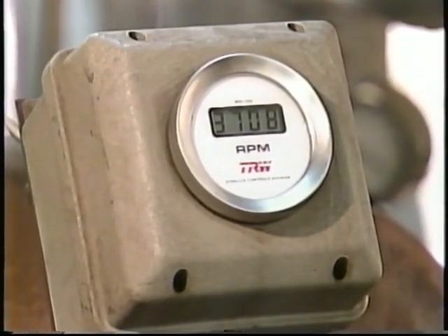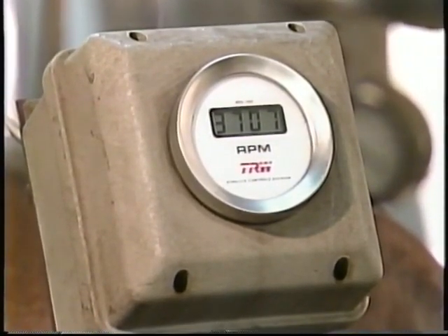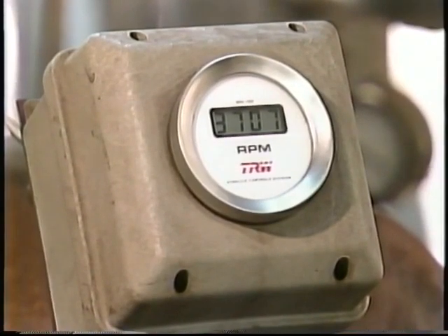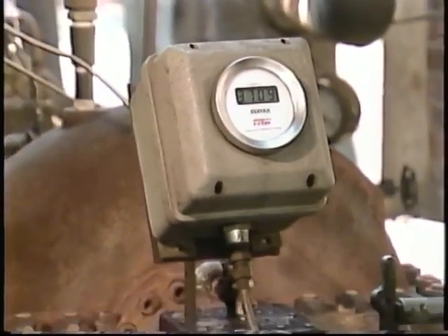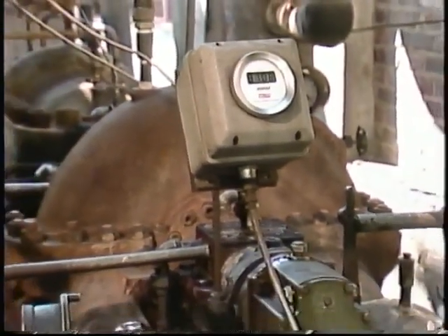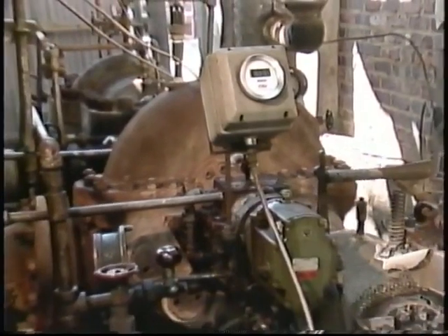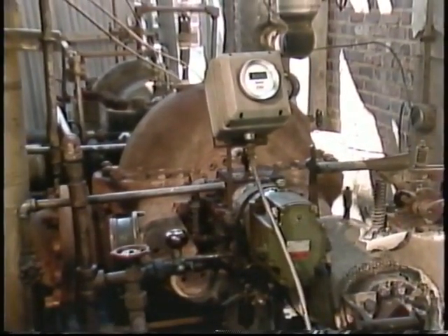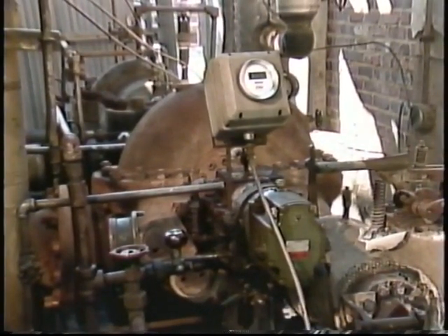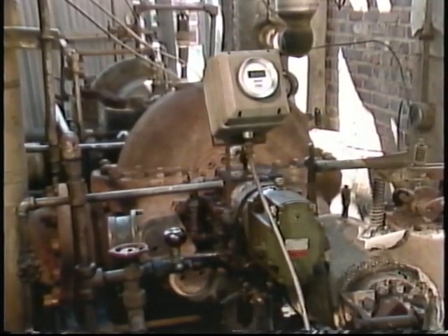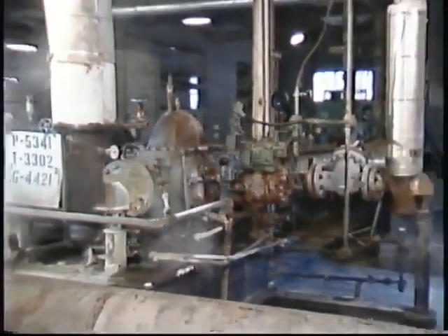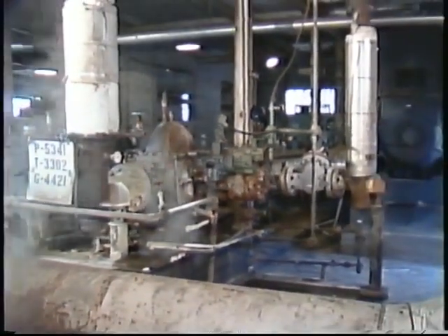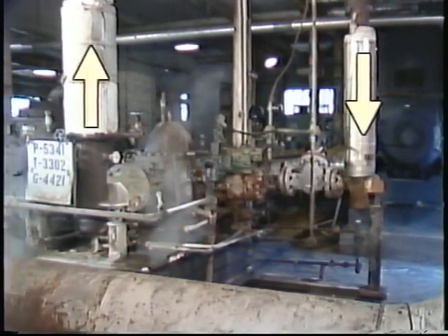When the turbine's running correctly, the RPM for the shaft speed is normal and steady with no hunting. Also, when the turbine is running the way it's supposed to, it makes a distinct sound that's unique to that turbine. You'll need to become familiar with the normal operating sound of the specific turbine you're working with. Then you'll be able to tell if the turbine doesn't sound like it's running properly. Finally, when the turbine is operating, pressures for the turbine casing and for the steam going into and coming out of the turbine may need to be monitored.